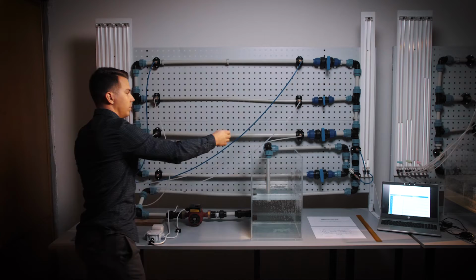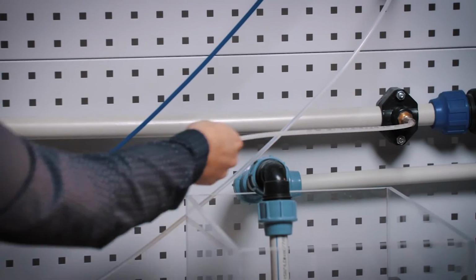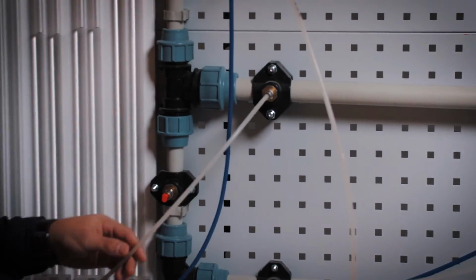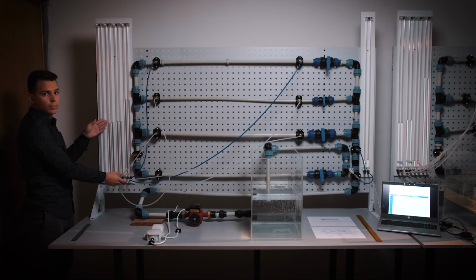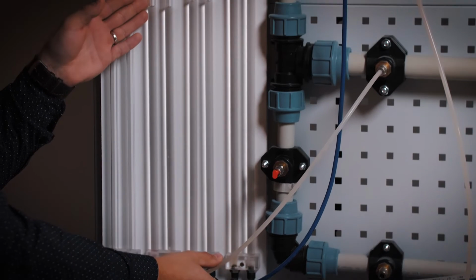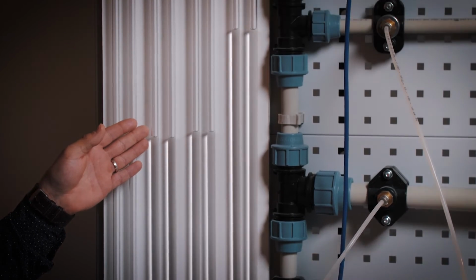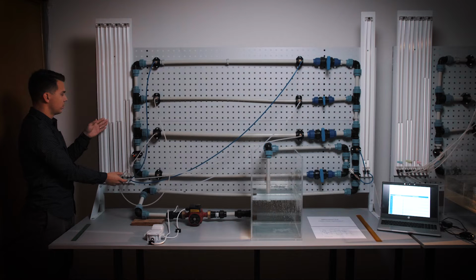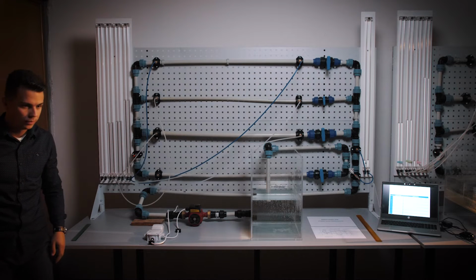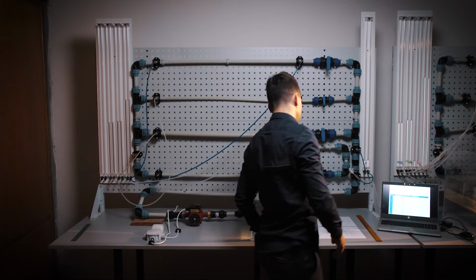The pressure points are connected by polyethylene hoses with piezometric tubes. The pressure drop is measured by using the pressure heights in the connected piezometric tubes. From the difference in the levels of both tubes, we determine the loss height. This can be further converted to pressure loss using the relationship for hydrostatic pressure.